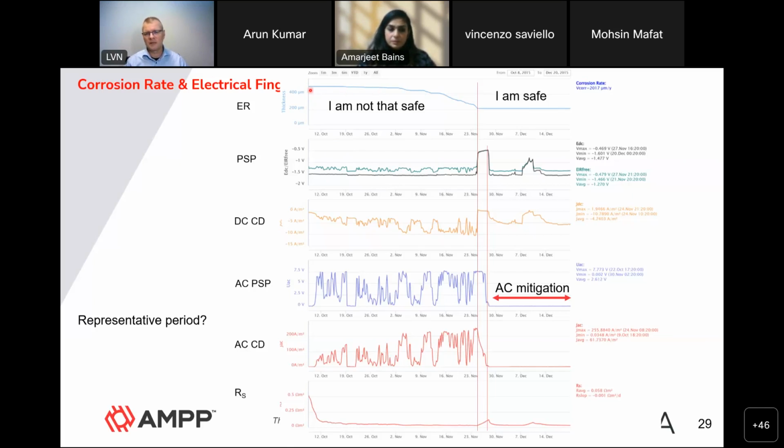And in case of any change in the thickness of the probe, you do have some kind of flag, a warning that something is going on. In that case, you might consider establishing a data logging so that you can start diagnosing what is actually the cause of this reduction. But clearly, an ER probe can be used in combination with data logging, remote monitoring, or spot-wise measurements.